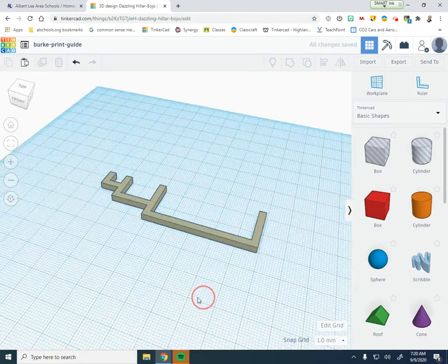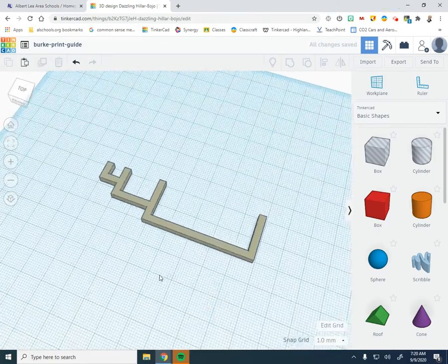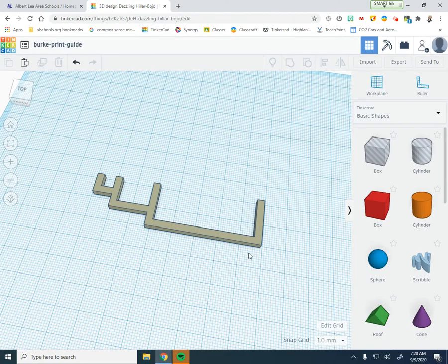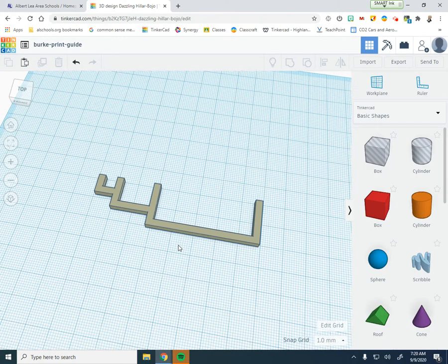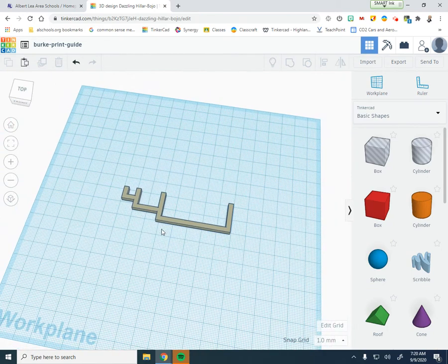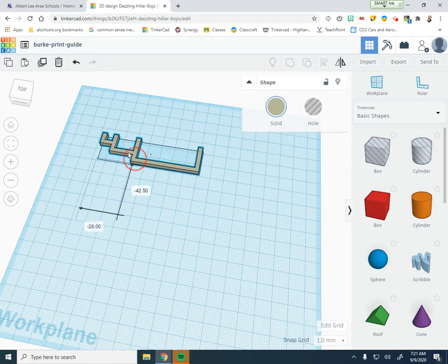Now what we've got here, if I go to look at this, the model will print perfectly without any of the drooping because I'm just printing it on the bed of the printer. Okay, so that's good. So that would eliminate having to do this. The same thing if you had your overhang model and you have that 90 degrees and all that extra ribbon of filament that's on the bottom of it, if we printed it on its side, we could print a perfect overhang model.